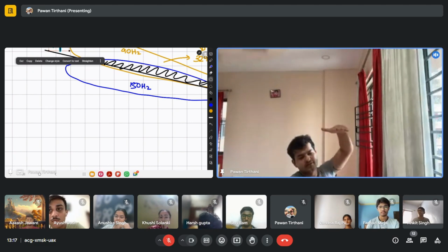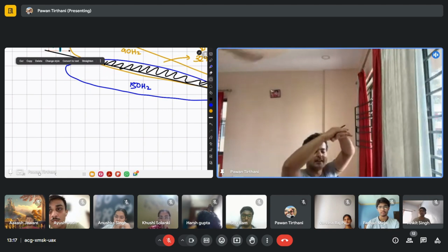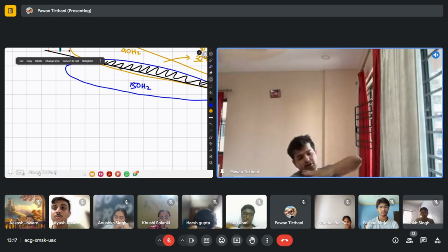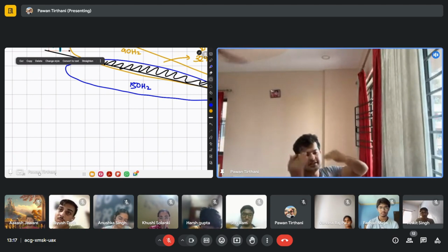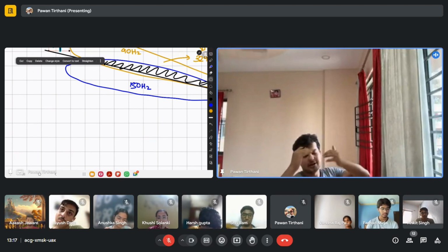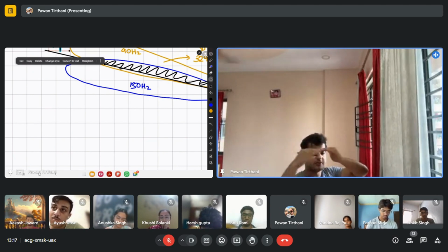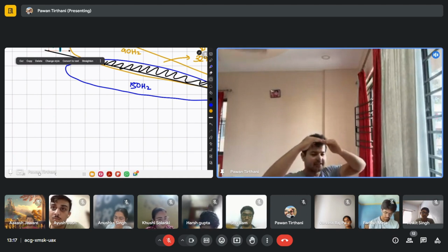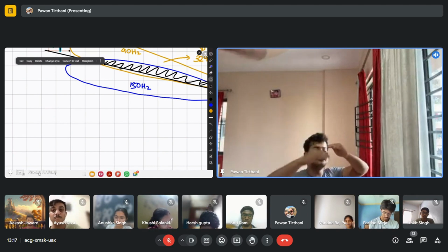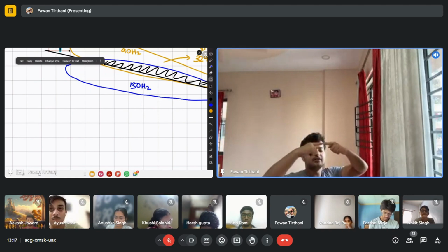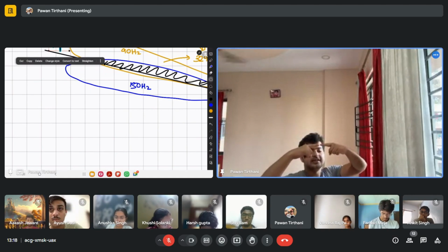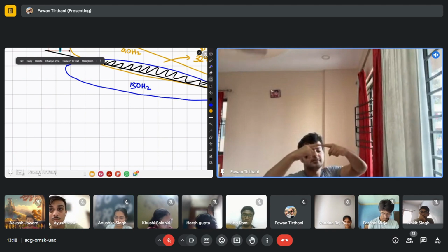If I'm receiving more of the 90 hertz modulation, that means I'm high. If I'm receiving more of 150 hertz, that means I'm low. If I'm receiving equal amounts of modulation, equal depth of modulation, that means I'm bang on the glide path. If I am receiving equal amount, there is no difference. My deviation will be 0. I am on the path. DDM, difference in depth of modulation, will be 0.